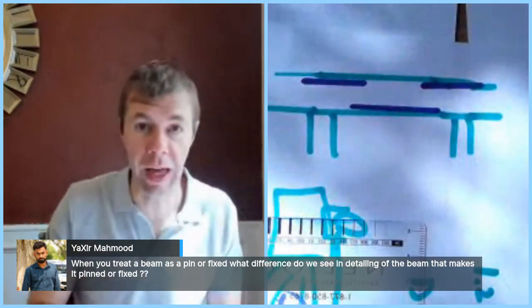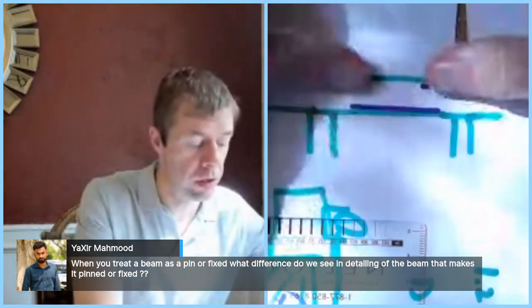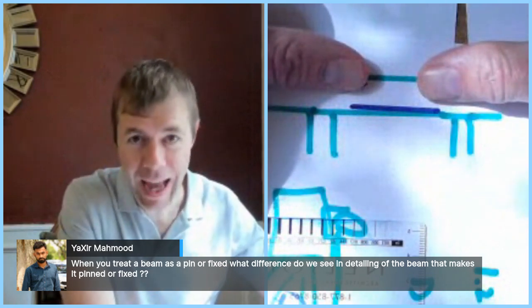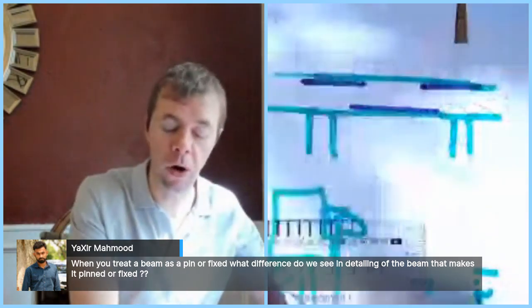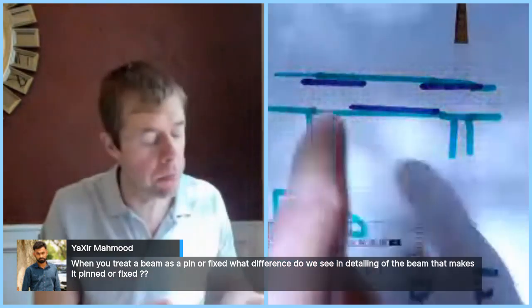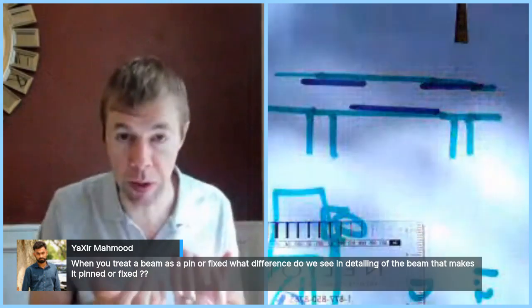If you design for that, that is how it will behave. Let's say you don't. Let's say you leave those bars out. That is how it will behave. That means there's tension here, but there's no bars there. It'll just cause cracks there. If the loads are small, the cracks will be small. If the loads are large, the cracks will be large.